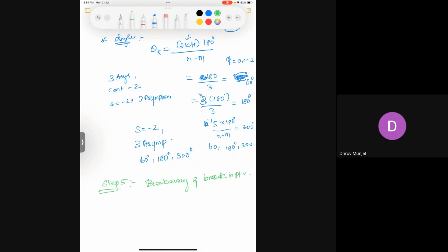This is where I told you, if a root locus lies in between 2 adjacent open loop poles, only I am speaking about open loop, not closed loop so far, everything is in open loop poles, in the real axis, then there exists at least one breakaway point.